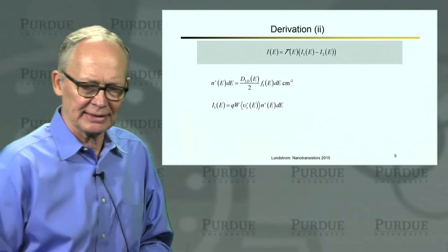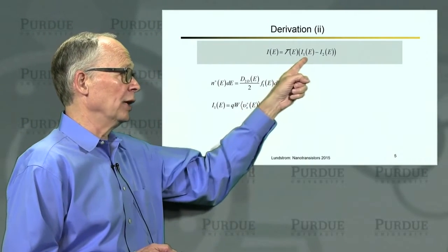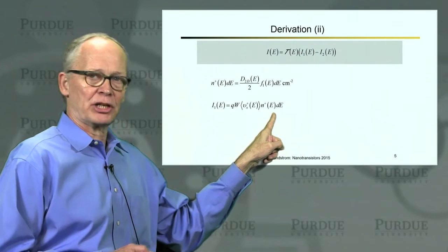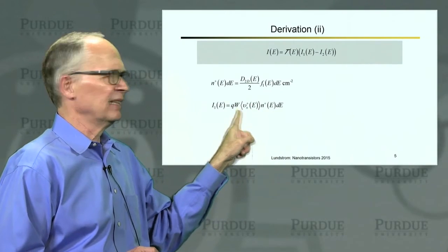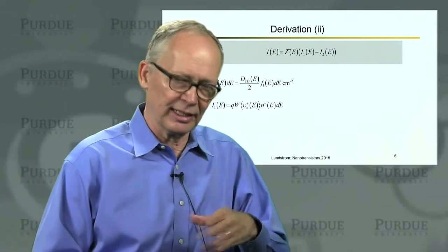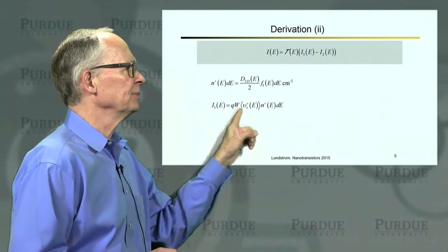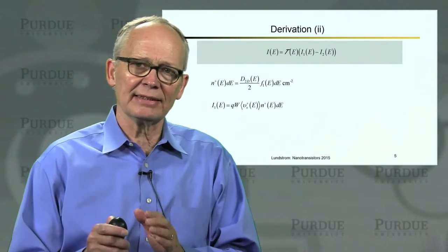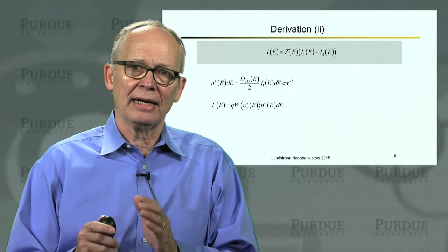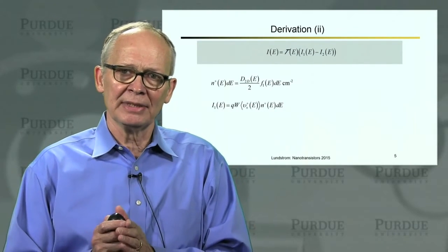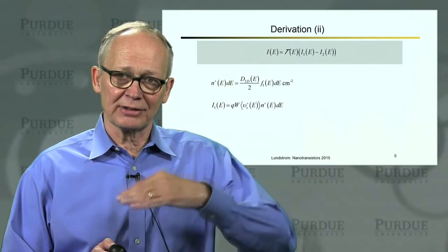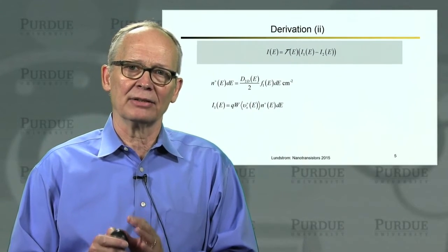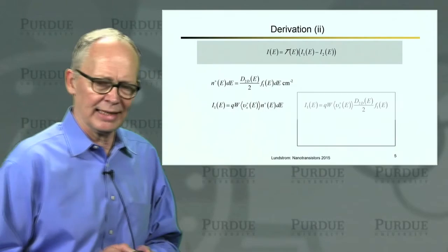And then if I want the current I1, I simply take the number, multiply it by Q because I have charge times velocity, and then the width, because the width is like resistors in parallel, so I have to have a width there. So this quantity, V sub x plus, this is the average velocity of the electrons that are coming in at that energy in the x direction. So remember, this is a two-dimensional structure. There's x and y directions. They might come in at an angle. The brackets here denote an average over angle. It's the average x-directed velocity. We'll talk about that in a minute.